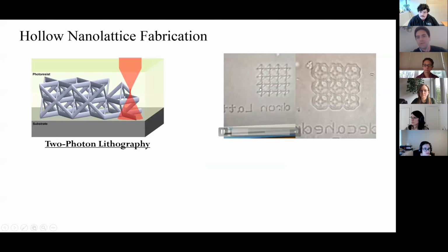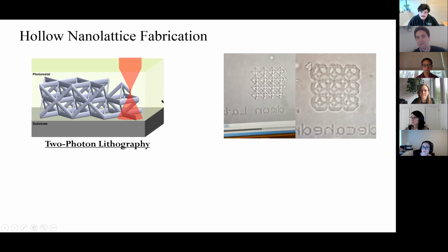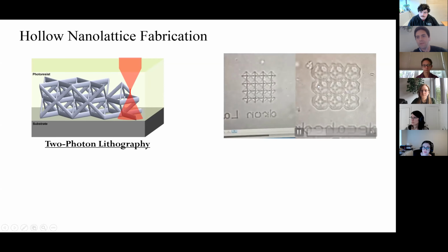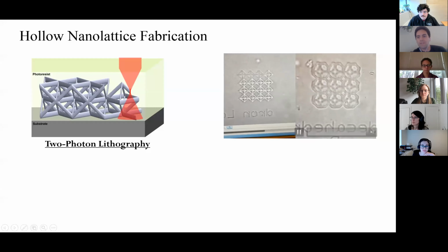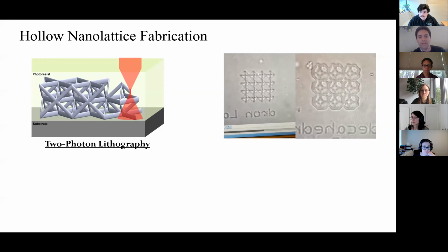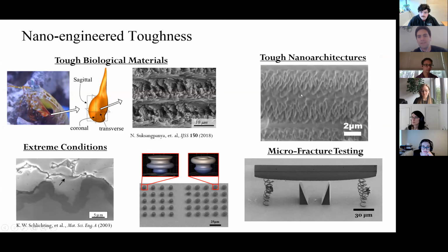So here with the 3D one, you end up with a solid polymer line that you can control pretty well. In the layer by layer method, generally it ends up pretty dense, but depending on the hatching and the layering, you can create things that do have some sort of porosity. So you can see here, we're actually intentionally introducing porosity into our structure.